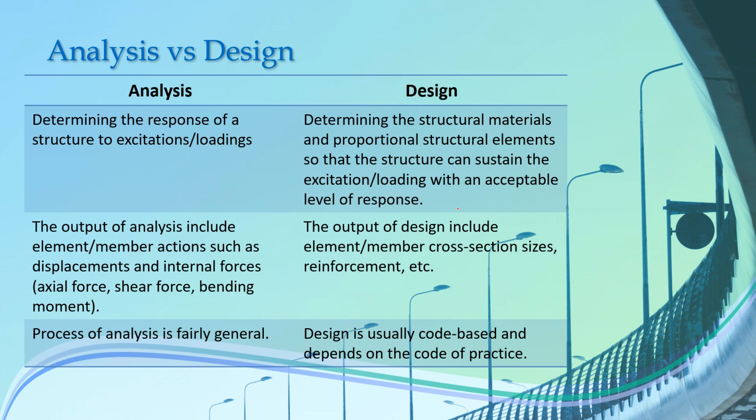So what is meant by design? We looked at the meaning of reinforced concrete. Now let's look at the meaning of design. Instead of looking at design separately, here I have made a table showing the differences between analysis and design. So what is analysis and what is design? Analysis means determining the response of a structure to excitations or loading, whereas design means determining the structural materials and proportioning of structural elements so that the structure can withstand the excitation or loading with an acceptable level of response.